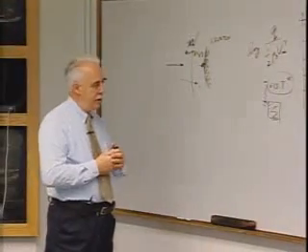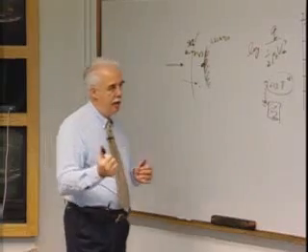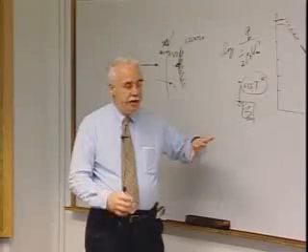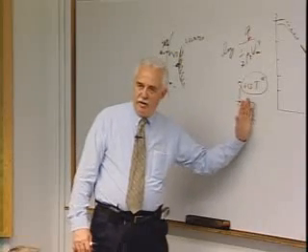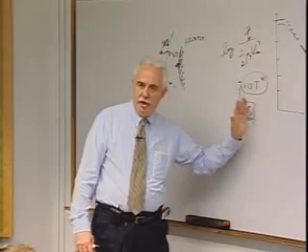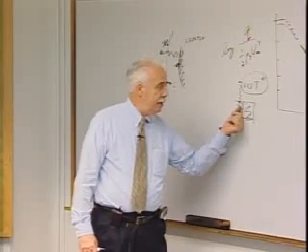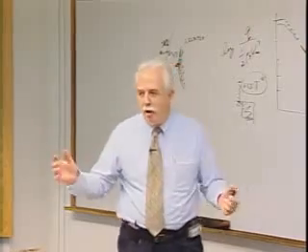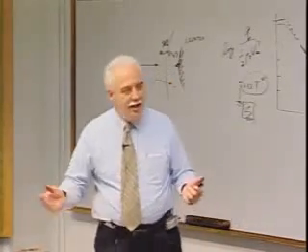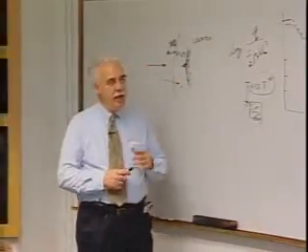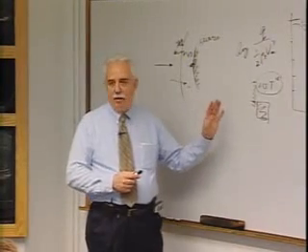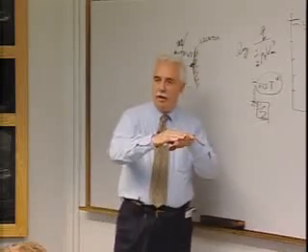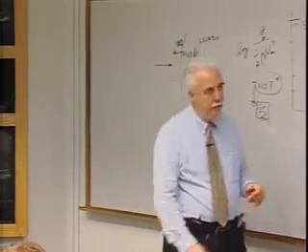Now, while I'm on that, the ablators were developed for capsules, and we kept getting lower and lower density because we wanted to minimize the diffusion of energy from the surface in. There needed to be a substantive enough surface to hang together. I mean, if you just have charcoal and blow on it, it's not going to stay there, okay? With the early capsules, with the Apollo, we had a fiberglass structure in there that basically retarded the ablator from flowing away.